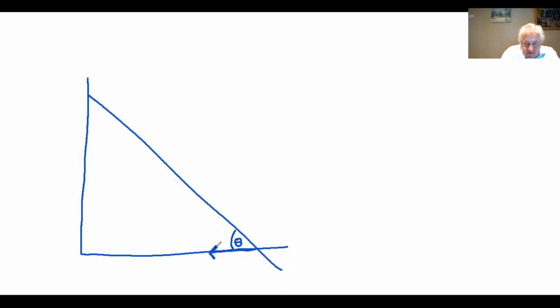So then I've got a frictional force acting here. Now I've got the weight of the ladder acting downwards, and the weight will act through the center of mass, and if the ladder is uniform, this will be halfway down. If we take the ladder to be of length L, this point will be at L over 2. Call this W, which equals mg. Now my only other forces that act are the normal reactions.